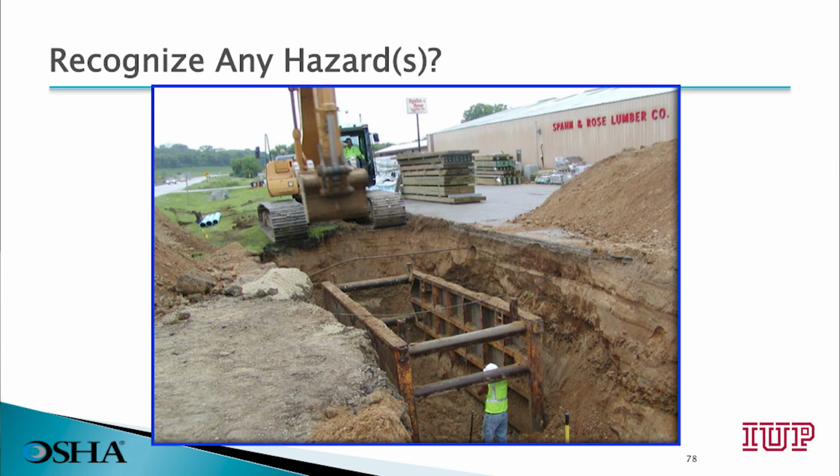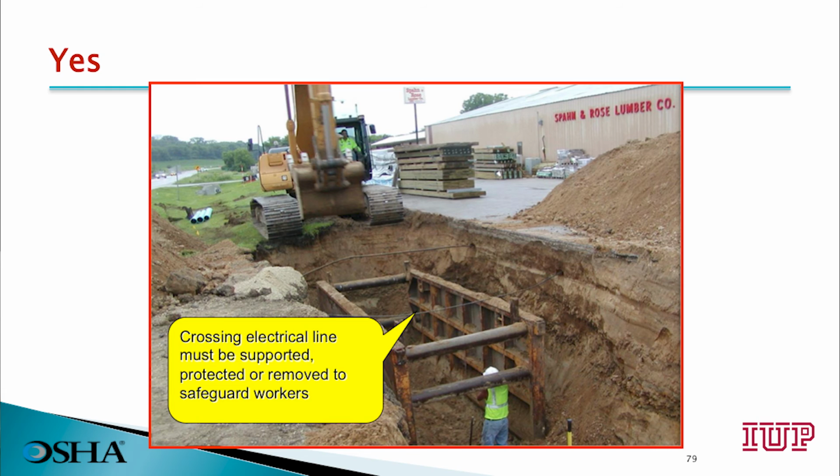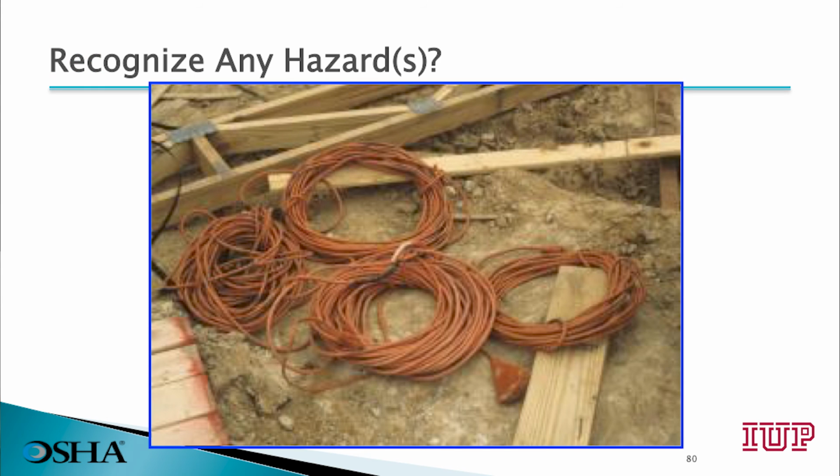If this is your job site, can you recognize any hazards? In this trench, we have crossing electrical lines that must be supported, protected, or removed to safeguard the workers working inside the trench. On this job site, can you recognize any hazards?